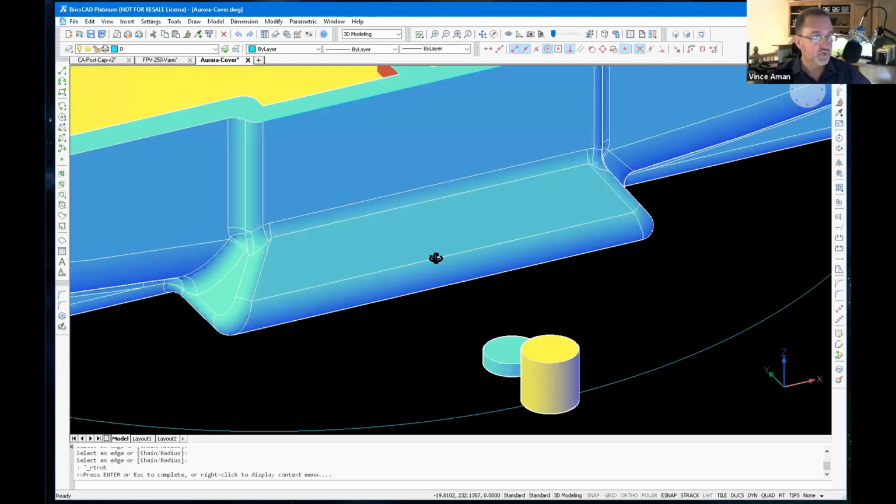The other thing I wanted to talk about, and you asked me about the interface, is that I like toolbars. Something that is often used are your object snaps. I don't know if you notice this, but the little blue boxes up here highlight the object snaps that are currently turned on. So it's really cool for me to look up and go, yeah, I'm using endpoint, midpoints, or you notice I don't have, if I just want to turn on my snapping to quadrants, it's simply toggling those on and off right there for object snaps, which I use all the time. And so just having that in the interface really works well.